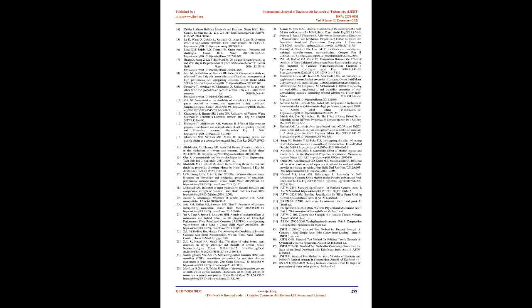CH% equals WLCH, % × MWCH/MWH2O, 53. Where WLCH is the percent weight loss of CH, MWCH is the molecular weight of CH, and MWH2O is the molecular weight of H2O. CH% content for mixes containing pozzolanic additions, NC and SF, is lower than the control mix, as shown in Fig 22. This confirms the efficiency of NC and SF in the first and second zones by promoting pozzolanic reaction that formed additional CSH by consuming CH crystals.